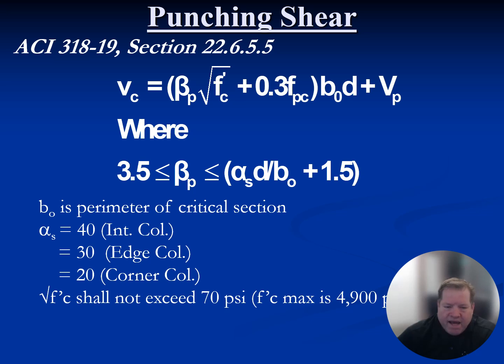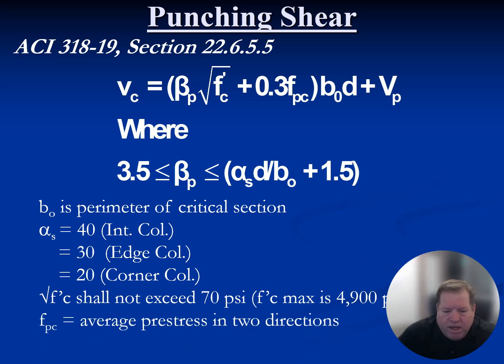What engineers have done is, when they're using higher strength concrete past 5,000, a lot of times they just go back to the regular non-PT equations for shear to benefit from that. But having said that, we are trying to change it. If you're doing a design and you go from 4,000, it doesn't work, you go to 5,000, doesn't work, and you go to 6,000, it still doesn't work, understand that after you've hit 5,000, you're not getting the benefit of an increase in compression.